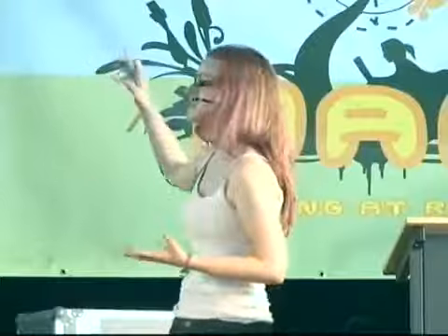So if you have access to SolidWorks or finite element software like ANSYS, it's useful to run a sim like that. That'll also tell you how many bolt holes you need. I did a bolt pattern of, I guess, 16 for that radius. Just make sure you don't have any large stress concentrations in the material.